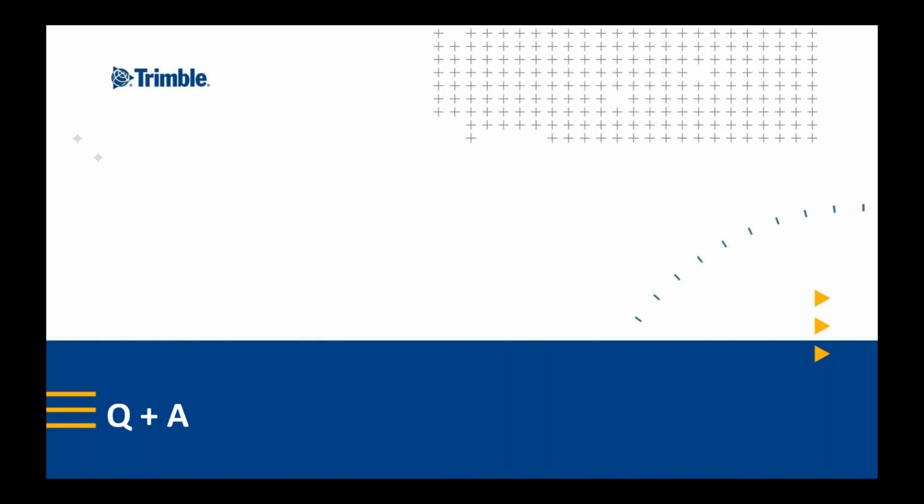It's not actually shown as super elevation as such in the road XML file. Everywhere that super elevation changes, just for us, is just different template definitions is how our workflow works.